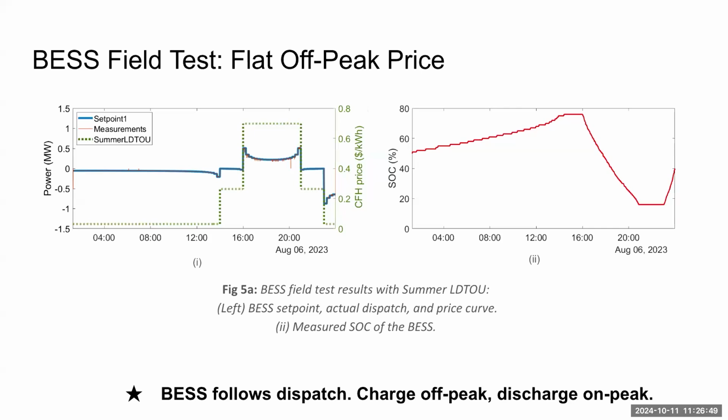Yeah. What factors are the drivers of degradation? Oh wow, that's a whole seminar in itself. I'm not an expert in this, but from what I understand it's the charging power. The higher power you have, the more degradation, and temperature. If the battery is not conditioned to be at the right temperature, say too cold or too hot, then you have higher degradation. Depth of discharge also. Yeah, that's right. Thanks. Yeah, there are some studies on electric cars on how the battery thermal management system has affected different car makes differently in terms of degradation. So Tesla versus Nissan and so on.